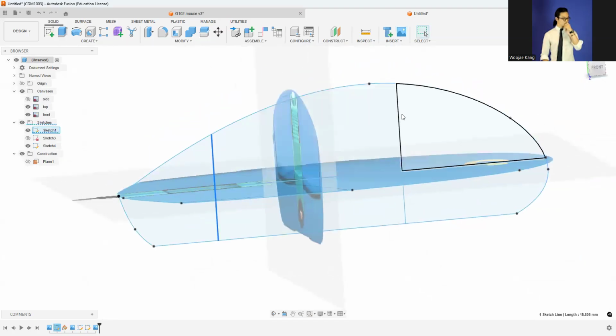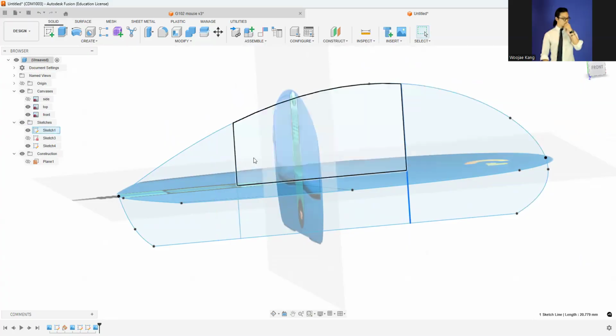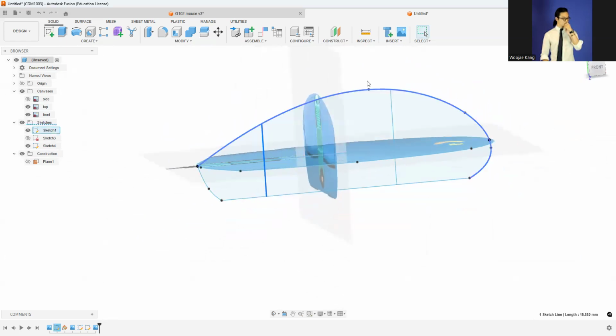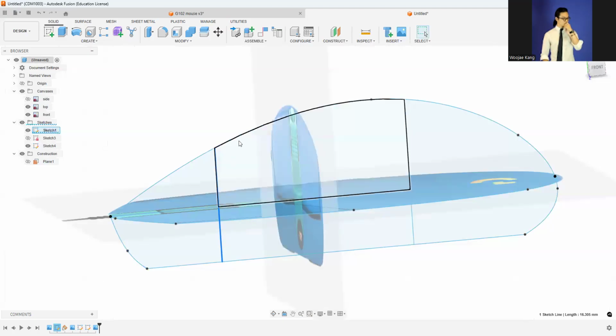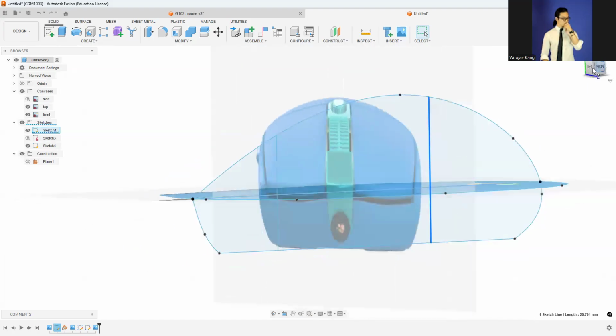The reason why I'm not going to sketch in here is because I want to sketch on this side and this direction. The distance is not proper, but try to just divide into 1/3 of each element, or some position that you think is more important. Because normally with this kind of complicated shape, more closures, like around closures, will help to make better shapes. And this kind of smooth curvature will be relatively easy to create without any errors. So that is why I distribute these two sections and these distances.